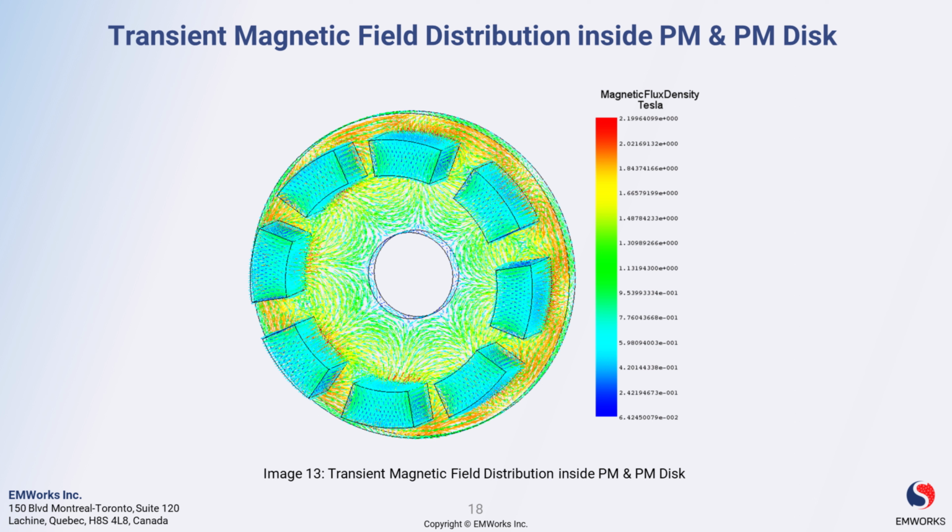So as researchers or engineers, what we visualize here is that we try to identify the regions of magnetic field concentration or saturation that may vary over time. Another parameter could be to analyze the dynamic flux paths and magnetic circuit behavior, which can impact the generation of eddy currents and resulting electromagnetic forces. Looking at this field distribution, we can also evaluate the potential of magnetic field leakage or interference with nearby components, enabling appropriate shielding or design modifications.